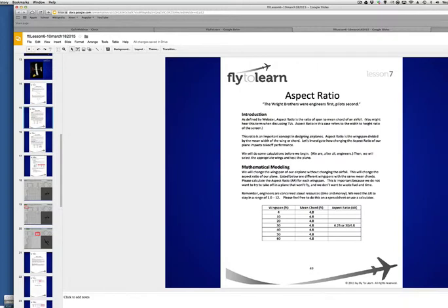But first thing we're going to do is find out which ones the plane will not fly. And so we take the wingspan and divide it by the mean chord. It's not quite accurate to say the average chord, but for right now, let's just say chord, which is the width of the wing. So wingspan is the length of the wing divided by the average width of the wing. All right? Or the mean of the wing is really better.